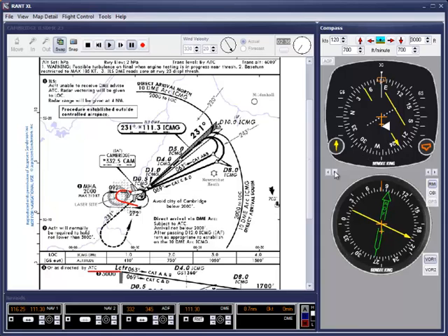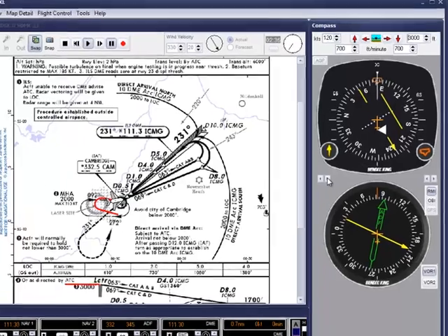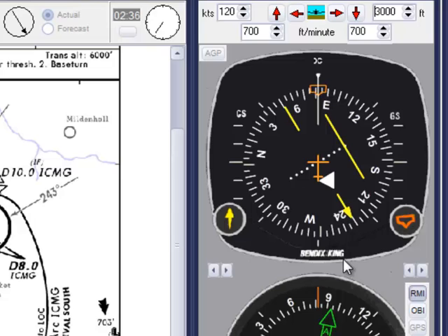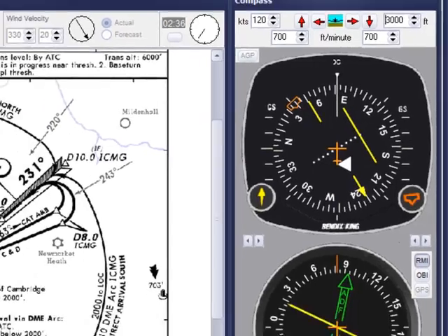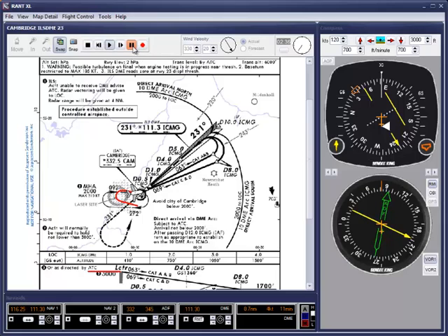Remember, it's from 330 at 20 knots, and I reckon that a heading of around 053 degrees should just about do it. As we're going to need to alter course by about 30 degrees to the left, I'm going to set the heading bug to 15 degrees beyond that heading, just to pick up the track at a reasonable rate, so that'll be 038. Remember, I can't descend until I'm within 5 degrees of track 063.